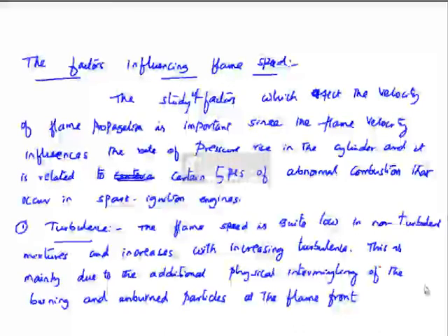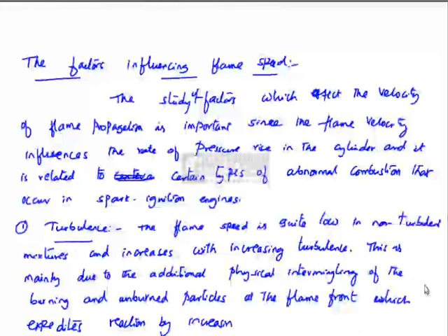Unburned particles at the flame front, which expedites reaction by increasing the rate of contact. In fact, having more turbulence, having more mix-up is definitely increasing the flame front velocity, because there is a better intermingling of the molecules of the petrol vapor and the air, thereby enhancing the rate of reaction.